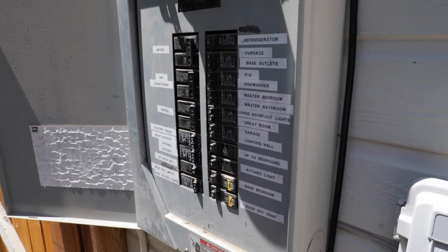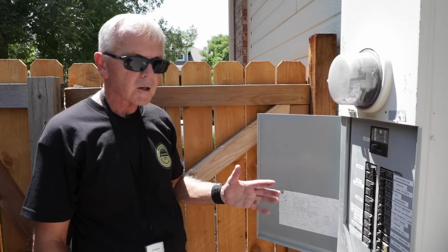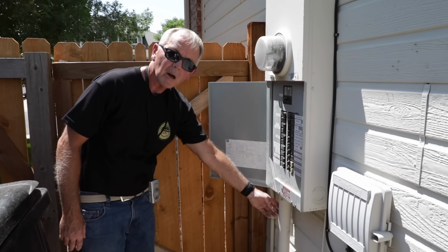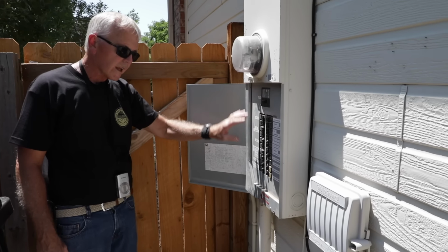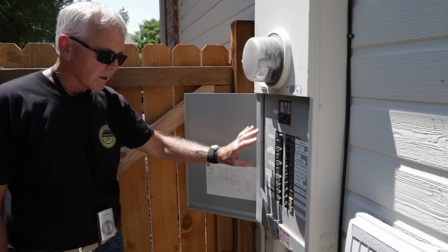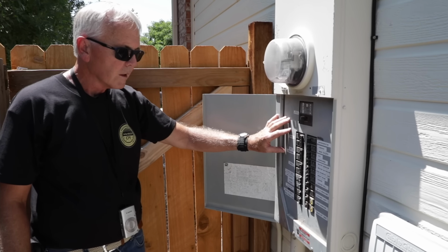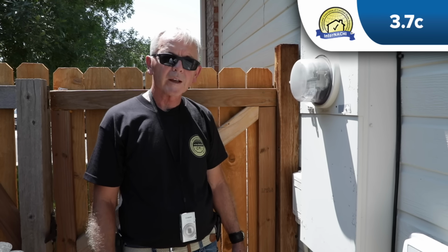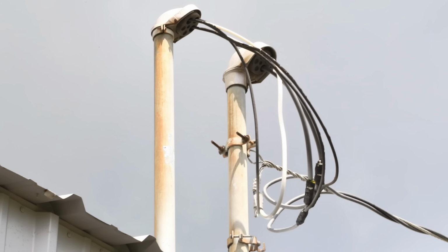They tested correct. In the SOP it talks about an overhead service drop, and on this particular house we don't have an overhead feed. Our service feed comes in from the bottom, and without pulling the dead front off I can't view those conductors. If I pull this dead front off I'm going to exceed the SOP. So in terms of this, we're not going to be able to put anything in for this. In terms of service head, gooseneck, and drip loops, there isn't any on this house. So we're going to put a reference photo in for you so you can see what they look like.